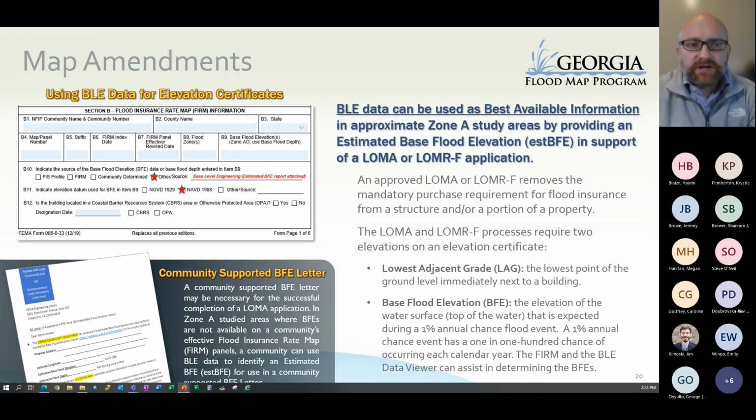The base level engineering can also be used to support LOMAs using the 1% water surface elevation from the base level engineering results to support LOMA applications. This may require a community supported BFE letter. So as BLE becomes more widely used and prevalent and available, you might find that there's requests from developers and folks to seek out a community supported BFE letter.